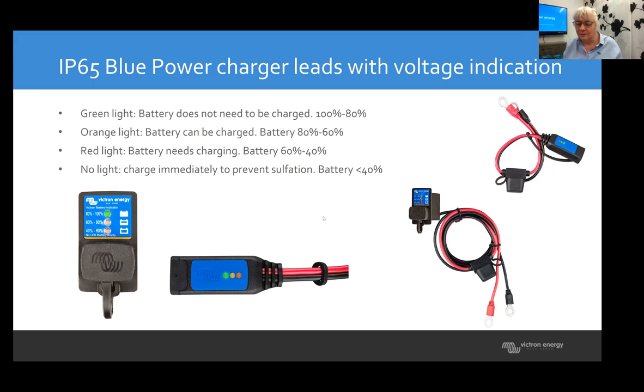That's just the process of the battery. And that can take up to half an hour, also depending on battery bank size and how big the load was. So voltage is not always an accurate thing. You might think, oops, my battery is empty, but then you see that the voltage has recovered 15 minutes later or something like that. So always measure a battery that's not in use for accurate monitoring.